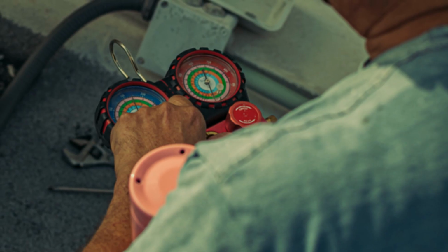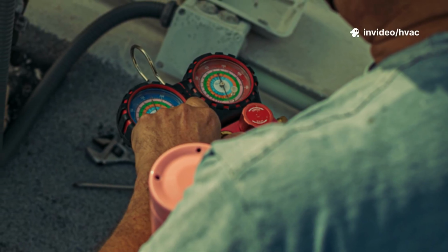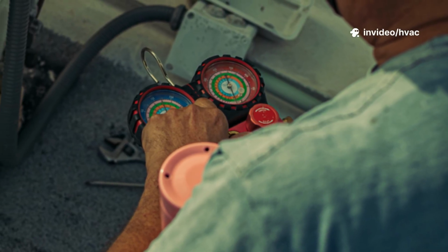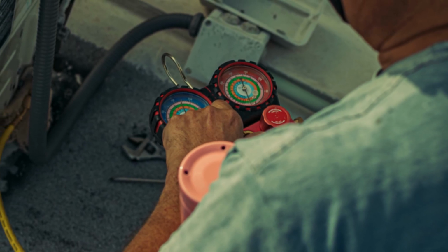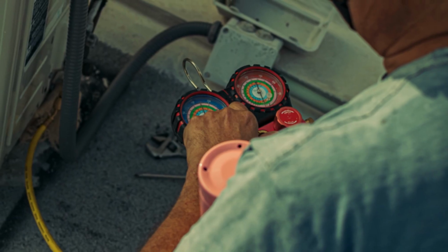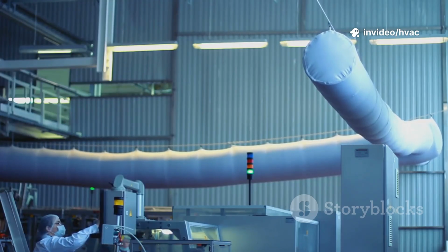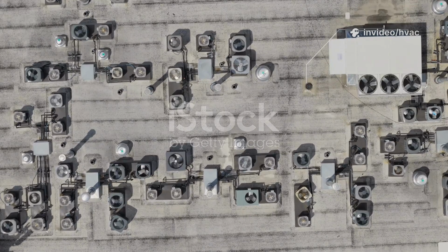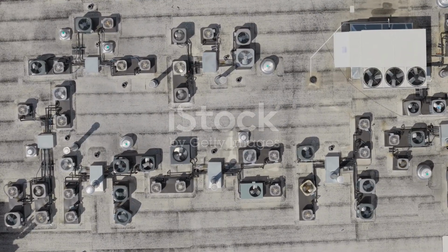Choosing between a capillary tube, a rigid rod, or an electronic sensor depends on your specific needs. Capillary tubes are simple and reliable, rigid rods are sturdy and great for straight runs, while electronic sensors can offer more precision and easier integration with digital systems. The key takeaway is this: to truly understand what's happening in your ductwork, you need to measure the whole area, not just a single point. Averaging sensors, whether capillary, rod, or electronic, make that possible.